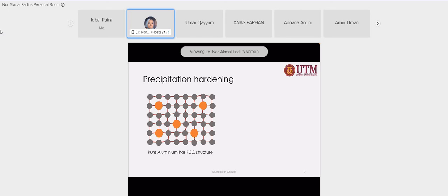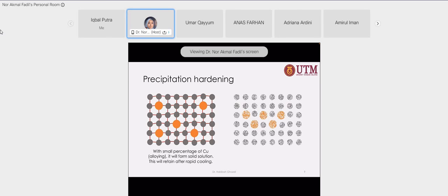It's not like solid solution hardening. In solid solution hardening, the atom itself becomes an obstacle. The foreign atom itself becomes an obstacle to the dislocation motion. How? Through the distortion of the lattice. Okay, you can see it distorts here, it is raised a little. So if from this side there is a slip plane, it moves smoothly until it reaches this distorted plane. It will slow down and then continue at the same rate, and then slow down and continue. Okay, just small effects.